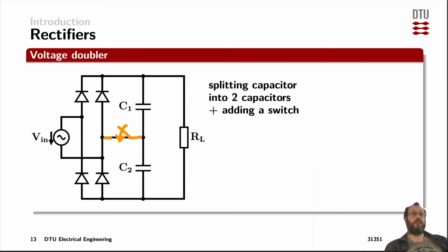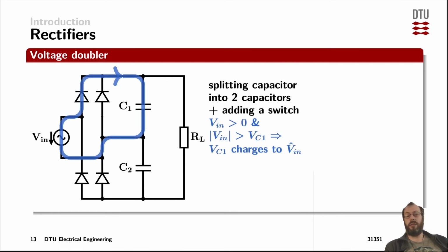Then we have a different circuit here. And what happens here is when the grid voltage is positive again, and again, it's got to be high enough to actually charge the capacitance. It's got to be high enough to forward bias this diode here. You would only charge the upper capacitor. So that's a half-wave rectifier, as we've seen previously, but still rectifying to the peak of the AC mains. So now if the AC mains are 110 volt, the peak would be around 155 volts in this case here. So that's what we're doing with the positive half wave of the grid.